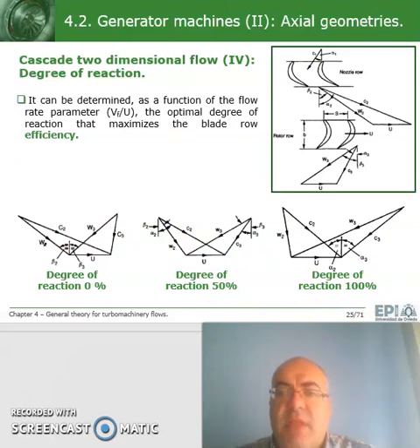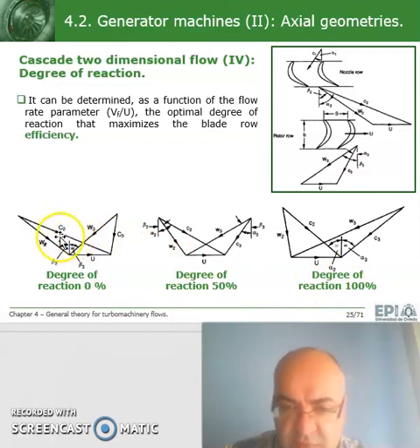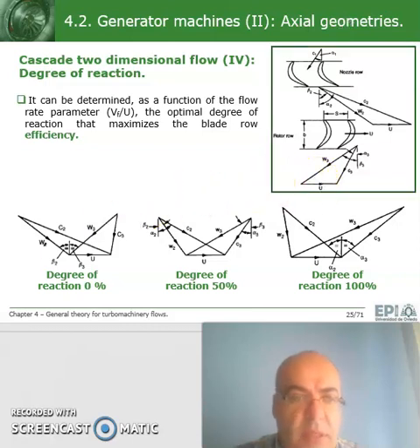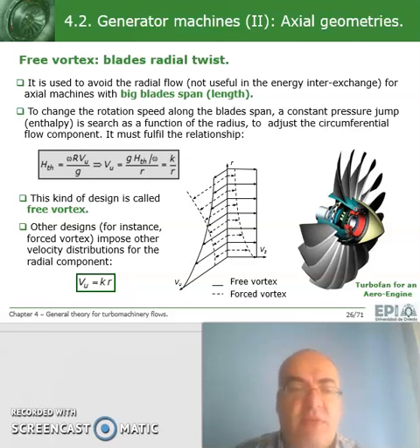And with the velocity triangles, we can also define the reaction degree in 3 steps, from 0 to 100%. So from 0 to 1, we have the typical shape that we should have on the velocity triangles to get that degree of reaction. Another example of the velocity triangles and cascade analysis, you have it here. You can work it out at home. For any questions, obviously, contact me at any time. Sure, feel free to contact me.